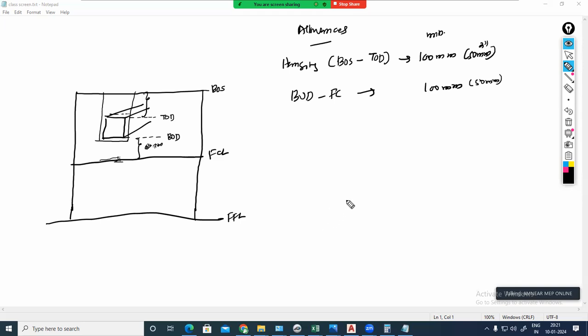The third one, thermal insulation. We will provide thermal insulation on the top side, bottom side, right side and left side. But left side and right side don't matter, because that affects the width of the duct only. Normally, we are finding the allowances with respect to the height only. Width, if it is mandatory, then rare only. Height only, we are facing issues. Above the false ceiling we have a lot of space in width, so we will not face much issue with width. We will be facing issues in height only. So that's why I am calculating the allowances in height.